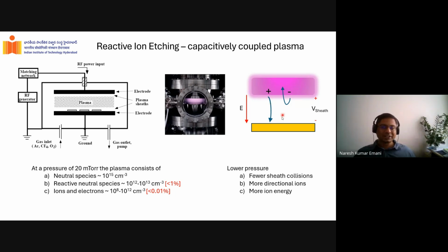So there's a small region near the surface of the wafer, which we call a sheath, wherein there's a strong electric field present. Okay, that's called a sheath here. So the electric field is what is represented here. Think of just the interface, right? Because your RF is causing the electrons to be ripped apart, and because they're very close to this, they quickly travel to this, and there is a small region where there is no plasma really, and then there is a voltage across that.